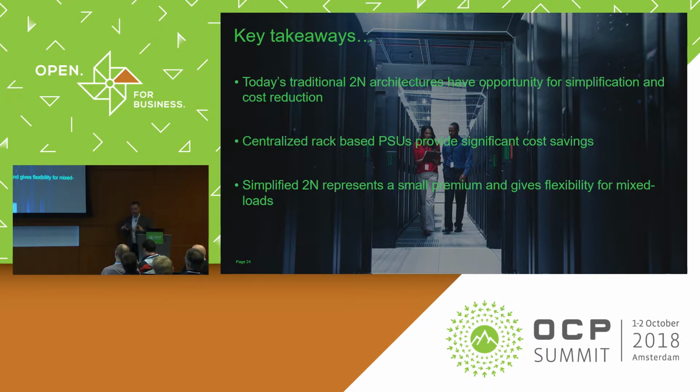Now, the cost of the rack-based PSU, if you look at just pure dollars per watt, is a little bit more expensive. But because of the savings from not oversizing, it's well worth it. And we think that a simplified 2N, and you can still, if you're trying to get open compute into an existing facility, you can still get a lot of the benefits of open compute, even though you still have maybe a centralized UPS there. And so those are the takeaways that we got from the study.